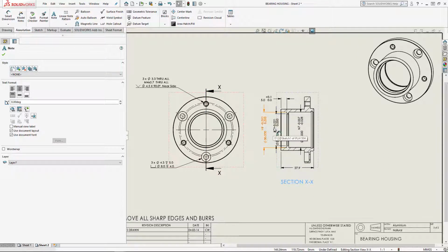And the reason that you would tolerance the part model and not tolerance the drawing is that wherever possible, the part model should kind of drive all the downstream activities that you want to do, essentially. So that's create drawings, create CNC programs from the parts or from the assemblies. Wherever possible, try and store as much data inside the parts themselves as you possibly can.